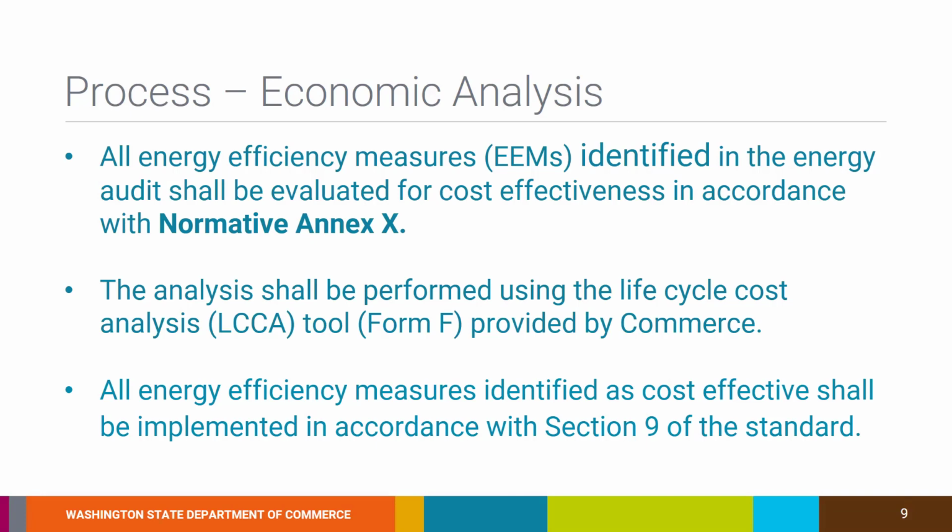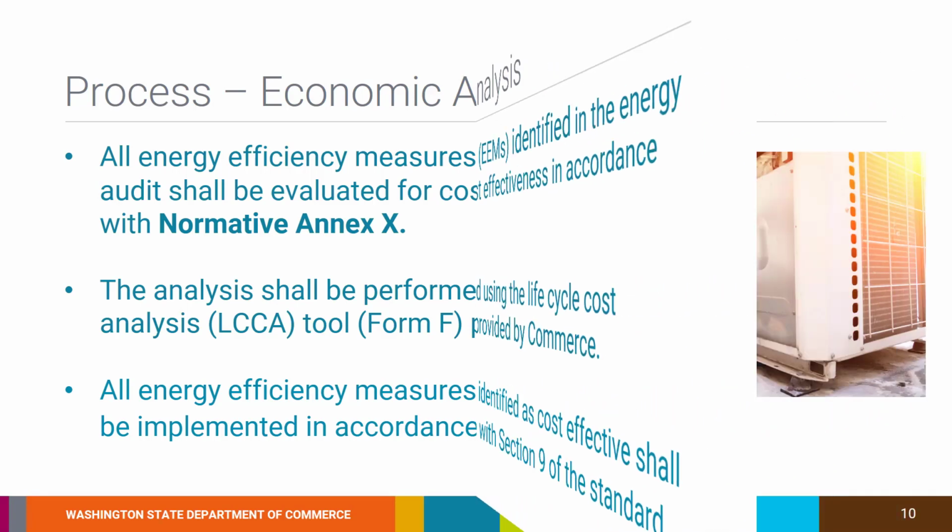This analysis is to include a life cycle cost analysis based on Section 5.5.2 and 5.5.3 of ASHRAE Standard 211 as modified by Annex X. The life cycle cost analysis shall be submitted using the life cycle cost analysis tool provided by Commerce. All energy efficiency measures identified as cost-effective shall be implemented in accordance with Section 9 of the standard.